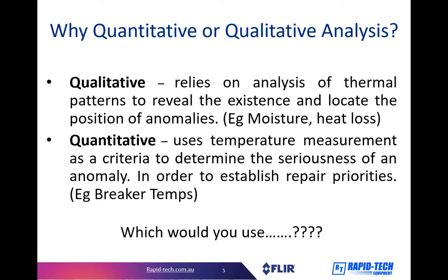For example, if there's a motor running, and it's above a certain temperature, that's when you can use a thermal camera to do a quantitative analysis. Whereas if you're, let's say, looking for water leaks behind a wall, it's not much about the temperature you're trying to read. Now you're doing a qualitative analysis because you're looking at a color difference. I'll go through some examples very shortly.